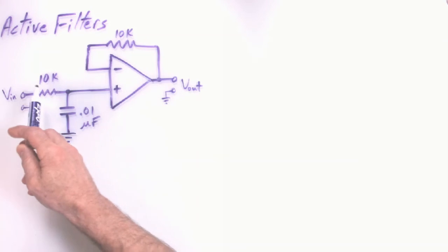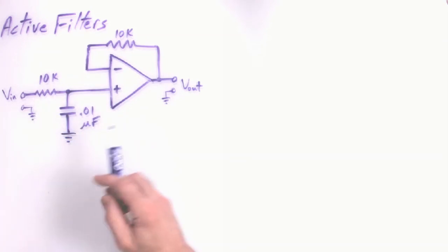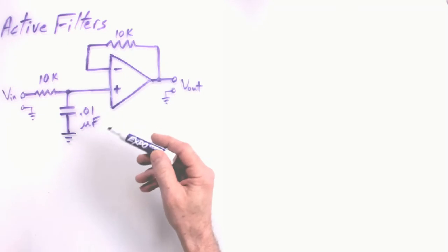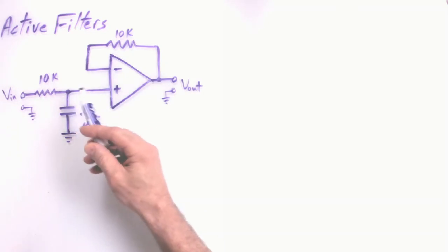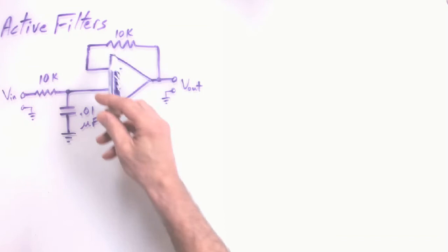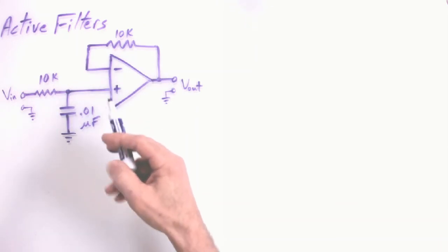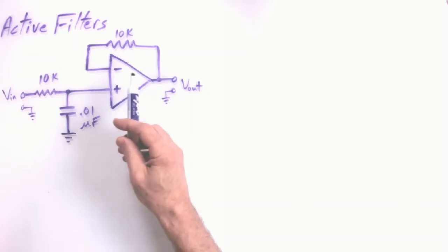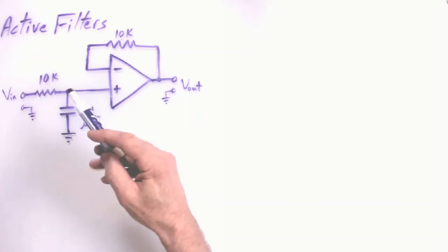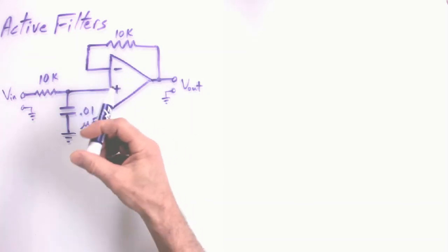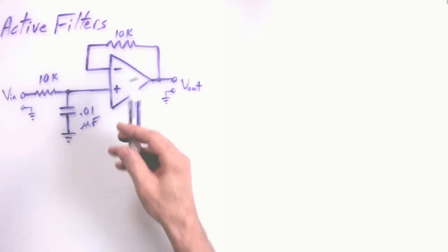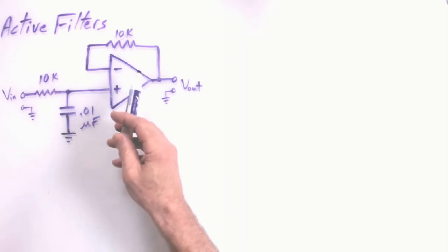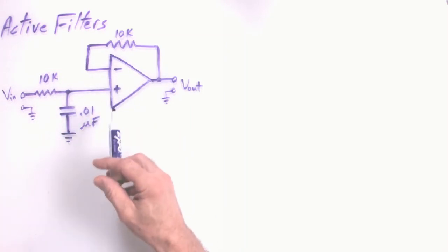We used, if you recall, a 10K and a 0.01 microfarad. And I've seen in many books on filters, I've seen this done. Like I say, I'm not an expert on that. I would suspect there's some benefits maybe as to symmetry, or maybe avoiding offsets, maybe reducing currents. If you think about it, that might all be sort of in the mix.